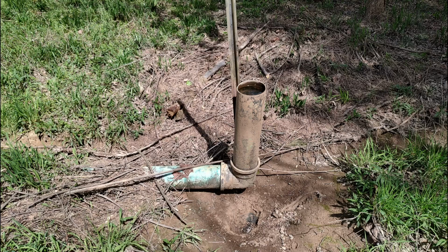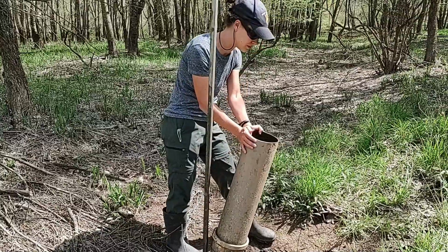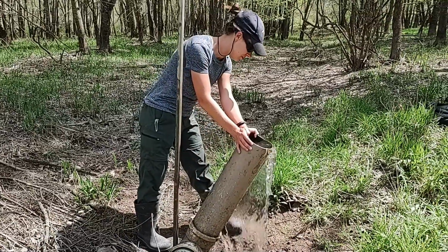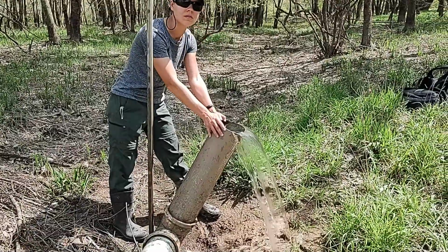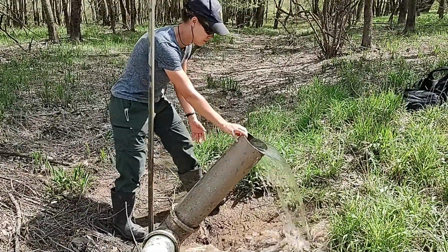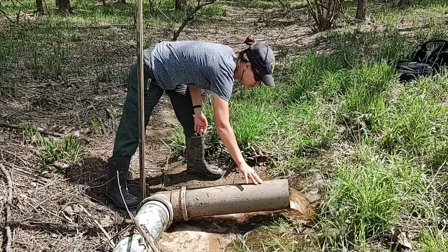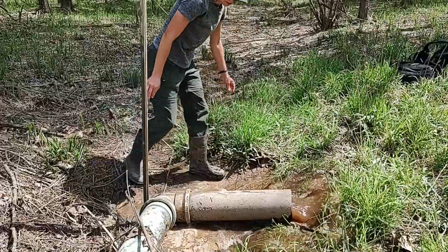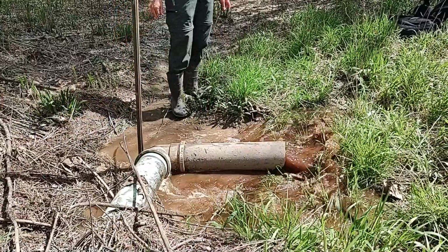The vertical pipe should be secured to the stake that's driven into the ground using galvanized wire so it won't rust. To drain the wetland, one simply moves the vertical pipe so that it's parallel to the ground. The rubber gaskets in the 90-degree fitting allow you to rotate the structure without leaking. To close the water control structure, you simply rotate the pipe in the upright position and then secure it to the post with a galvanized wire.